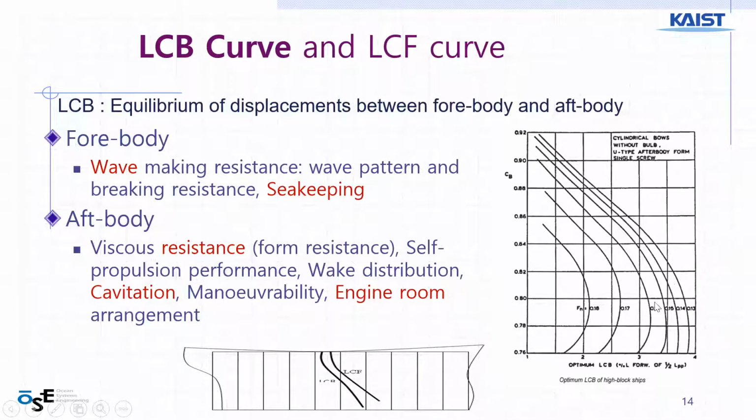And the right-hand side is also LCB, but with the Froude number shown, the optimum LCB is shown here, and the block coefficient. So as a designer, you can use such a graph to determine your optimal LCB as a reference for your design.